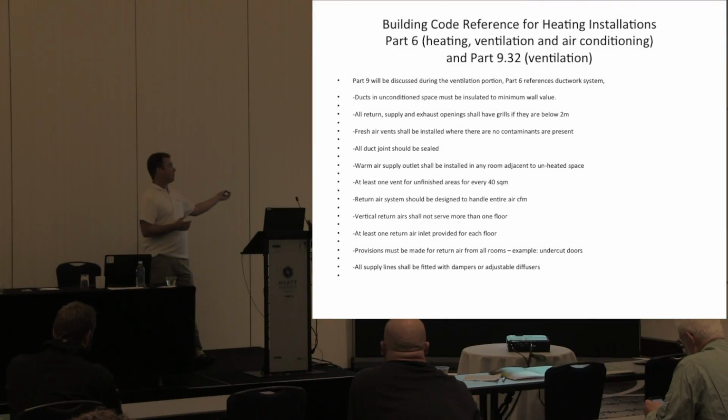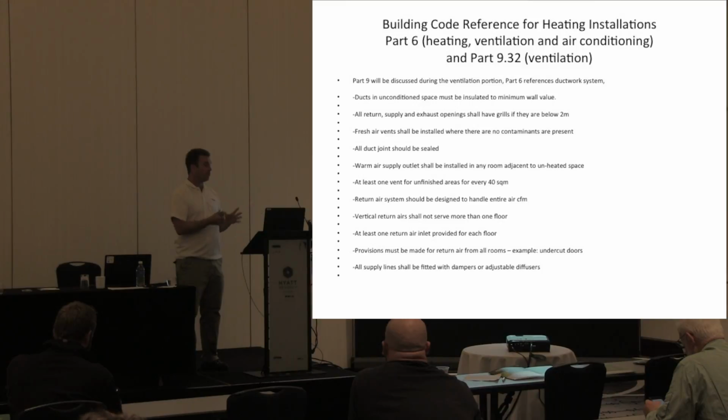The parts of this, it was always supposed to be there. Now there's actual rules about how much, which you guys would have done if you've sat in the 9.36 class for how much you're supposed to do. You need to insulate it to the R value of the wall now. All returns, and we can't run up outside walls anymore because we need to keep the R value of the wall, all those kinds of things. I'm not going to go over too much of the energy efficiency stuff.